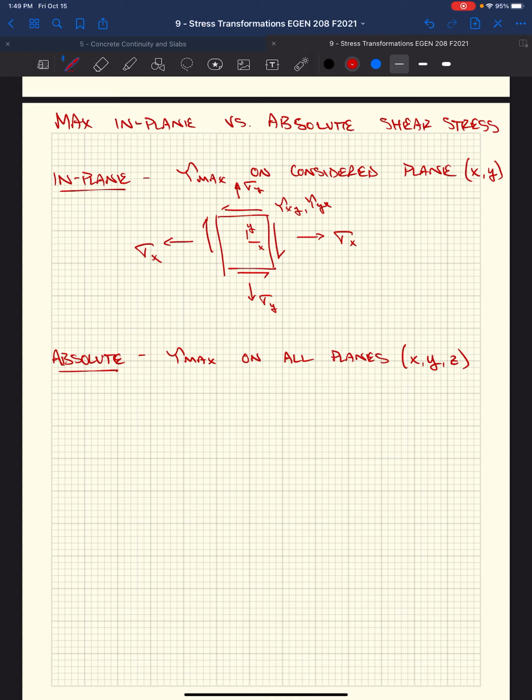Okay, so I brought this box because it took me a second to visualize this. Say this was our stress block, and we've been really looking at stresses on all 4 of these sides. Say this is the x-axis, this is the y-axis, just like I drew it. And we've been looking at if we were to cut our flagpole at an angle, we were able to calculate based on Mohr's circle what these stresses are going to be on these 4 sides. And we're going to continue to assume that we're dealing with plane stress.